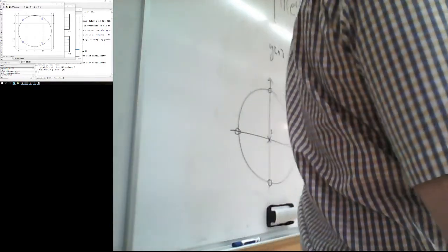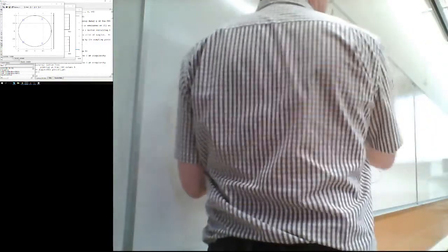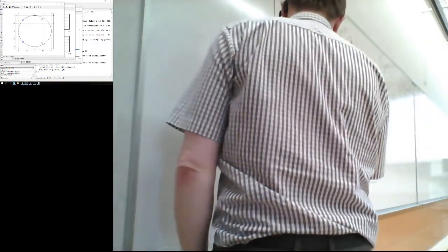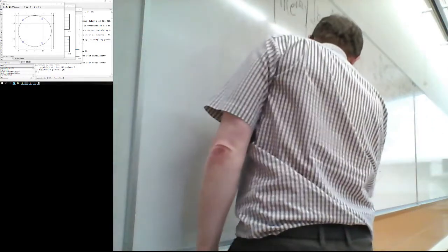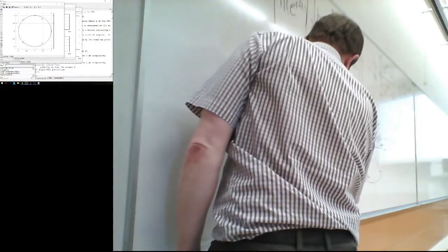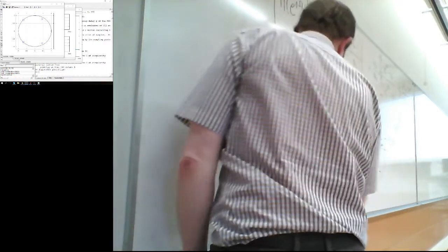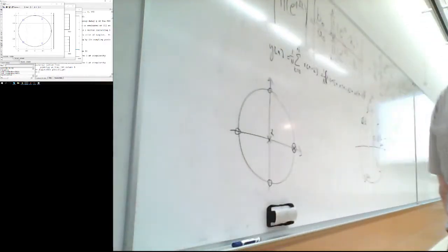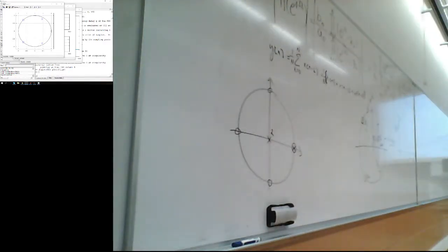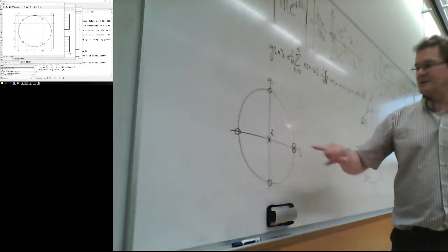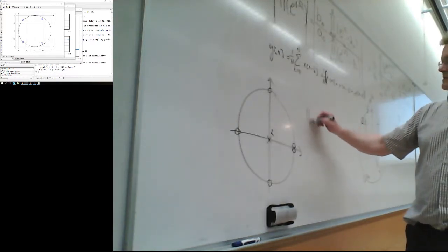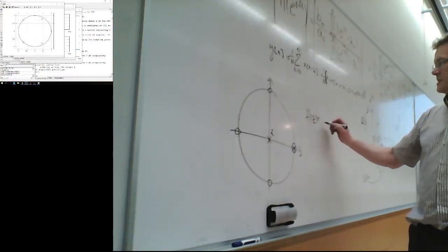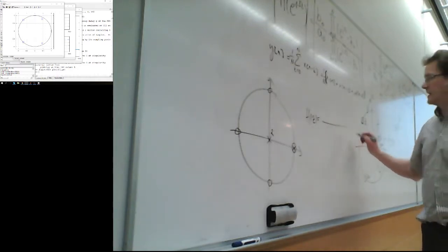How to make the same system so it's recursive, but still FIR. You take one of those poles right here and also the corresponding zero, and you cancel it. What did I do here? Did I do something wrong? No, I didn't. But the transfer function comes out actually quite nice.